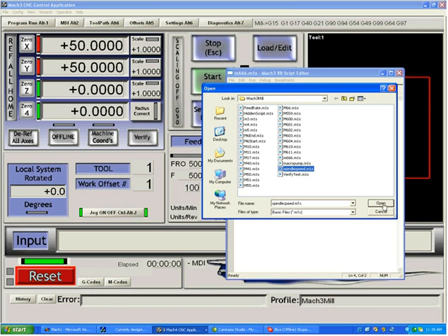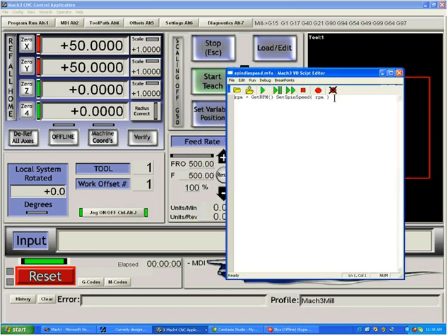For example, here under spindlespeed.m1s, this is a script which is called whenever you set a spindle speed. So when you type S600 in your MDI line or in a G-code program, we will use the command RPM equals GetRPM, which puts the value of that S600 command, or the 600 portion of it, into a variable called RPM. We then set the spindle speed to that RPM.